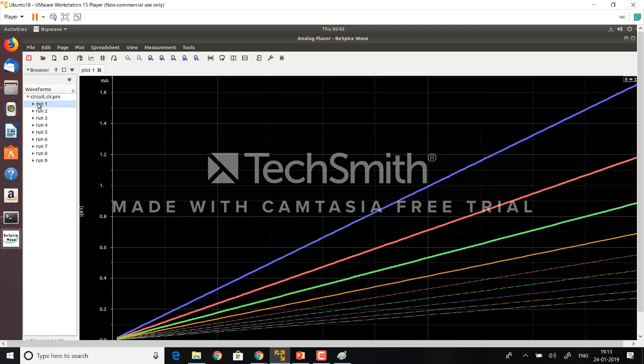So if there's self-heating in the device, I should see something like this, right? As the currents go up, its resistance should increase and the current should decrease. So it should make something like this, right? That should be a self-heating behavior.